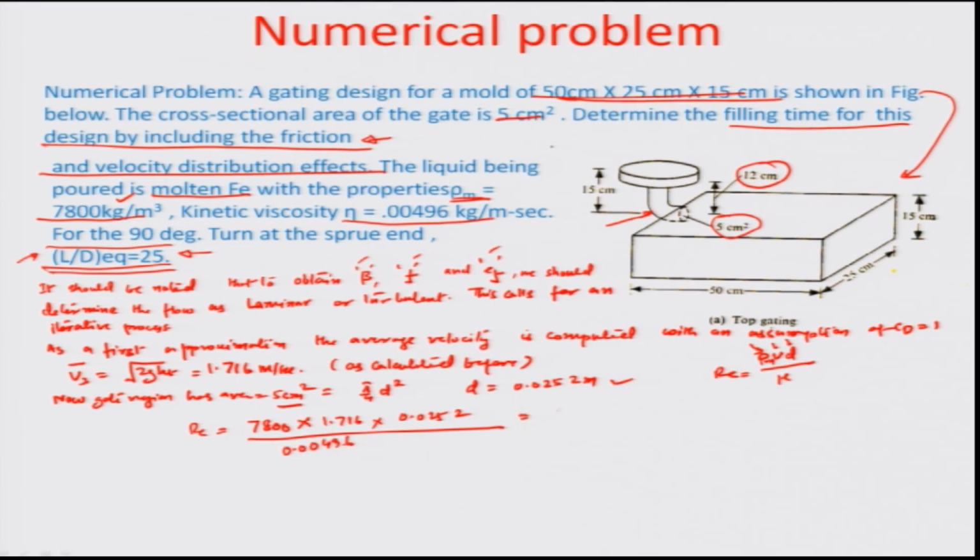And so, that becomes equal to a Reynolds number of about 68,000, which is actually determining the flow as turbulent, even though there is no wall friction. So, this is very interesting that the flow is seen to be turbulent by the first estimation without the use of any friction. Now, let us start the analysis.